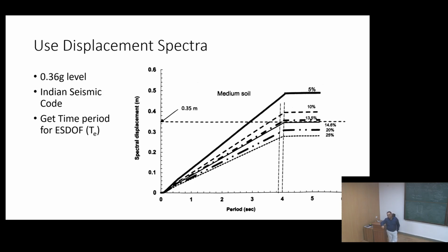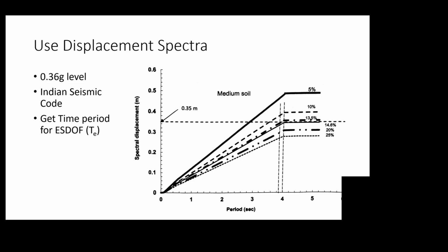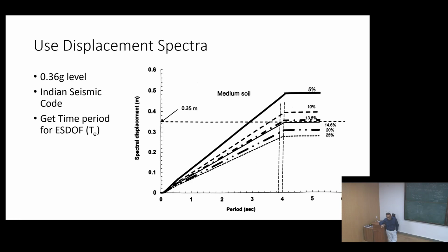So what extra steps are there between just a frame structure and a dual frame structure? We have to calculate everything separately for frame and wall, then we have to find equivalent values. Yes. So you have to calculate a lot of things differently or separately for frame and wall and then combine it together for the system itself. Your shape function is different. Shape function is now governed by the wall's yielding. The rest of the concepts are pretty much the same.